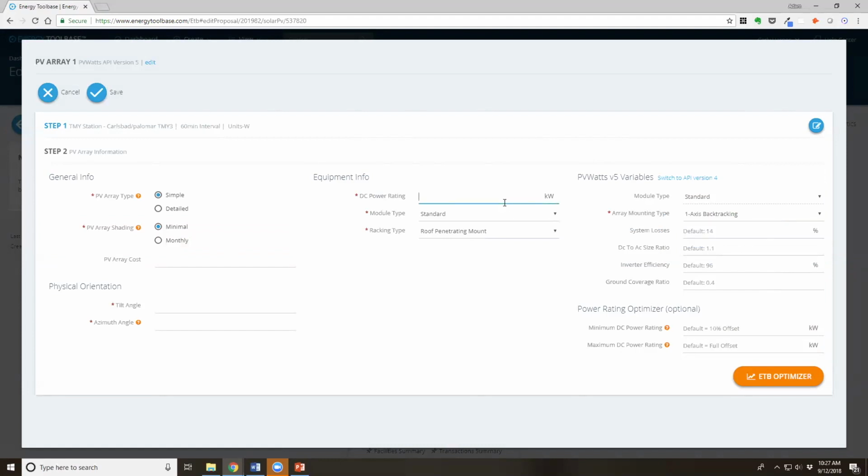So we'll use the same system size, 503 kW DC. Per the PV Booster design guide, we're going to run this at a 30-degree tilt, 180 azimuth, and maybe Conrad can talk on that when he comes back on in a minute.